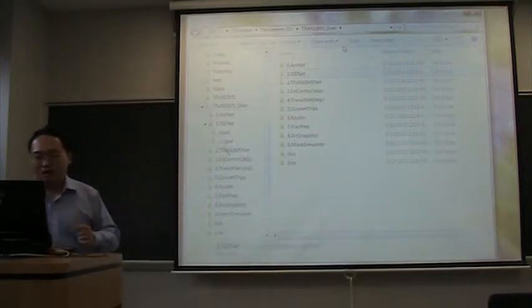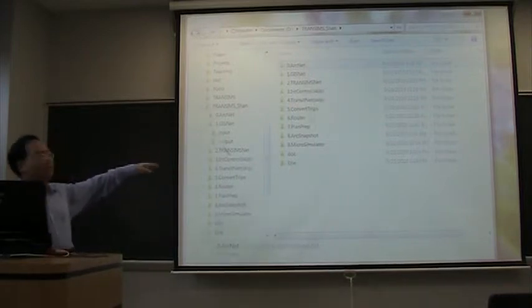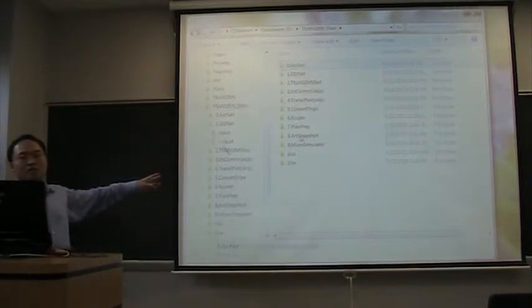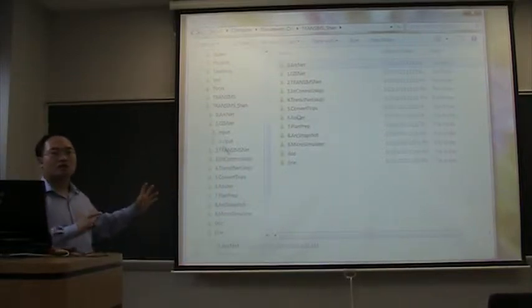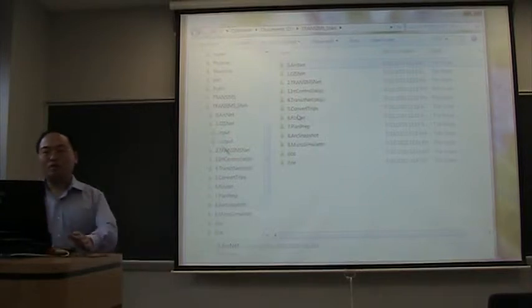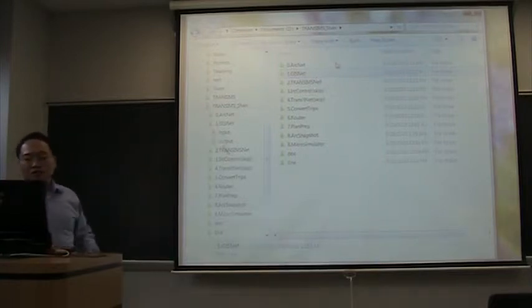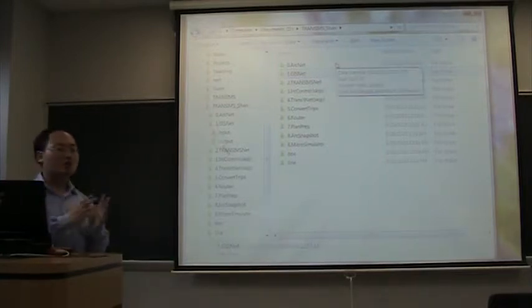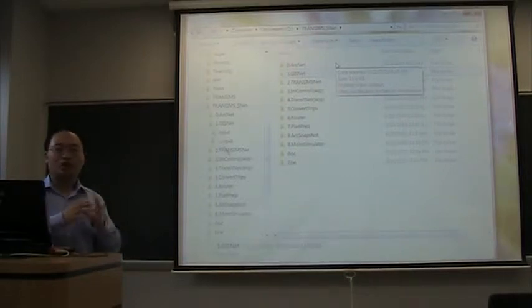This is the folder I will be uploading today. So you see numbers 0, 1, 2, 3, 4, 5. The number at the beginning of the folder indicates the sequence of tools that you want to execute. And we start with tool 1, not tool 0, called gsnap. gsnap is for converting the shapefile I just cut into generic network files.